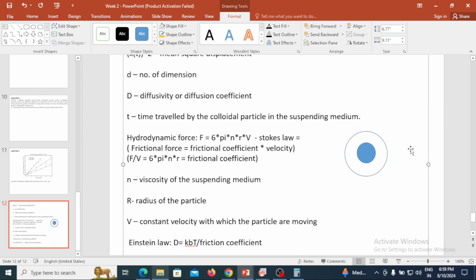Another thing that you can calculate is the zeta potential. For that we take a special sample holder called a cuvette. That cuvette has gold plating on either side, and you disperse your liquid solution through the cuvette and then apply the electric field.